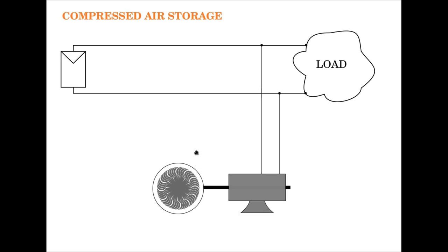So the air compressor takes in the ambient air, atmospheric air, compresses it and puts it into a container through a non-return valve. So it will push the compressed air into this container, and the pressure within the container keeps increasing at a constant volume, and you store the energy in the form of P into V, pressure into the discharge volume.